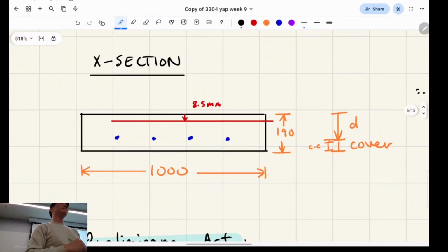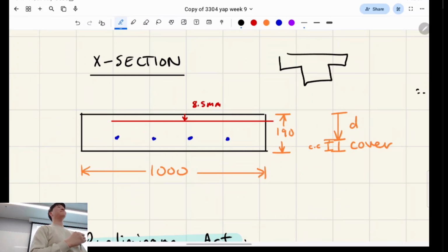It happens to be into that. Is that necessarily harder to calculate, or... are you talking about flexure, shear? Yes. But we're not doing a T-beam at the moment, but I know what you mean. You mean for a T-beam, right? Yeah. It is harder because you need to calculate the strength of the compressive concrete, which is basically this area, right?